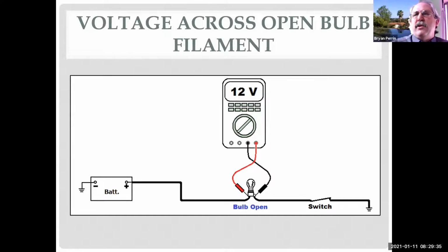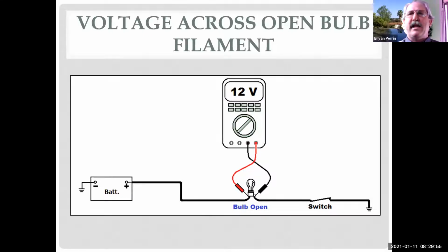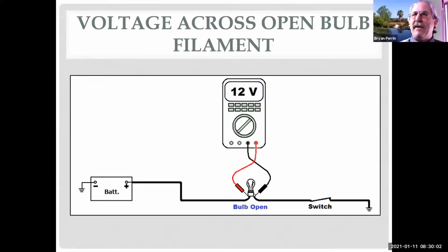And you think about it, don't we do that at home all the time? If I plug the microwave in and the microwave doesn't work, and then I unplug the microwave, but I plug the toaster into the same outlet and the toaster works fine, do I figure out the microwave's broken? Yes. But I don't know how the microwave works inside, but yet I was magically able to figure out it's broken, right? Yeah. And I did that by what? Proving that it has power by using a different load.